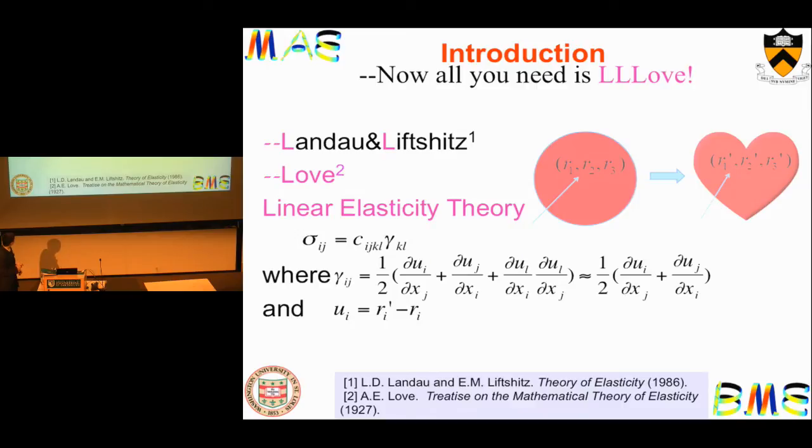And in linear elasticity theory, people just throw out the higher order terms, and the constitutive law simply states that the stresses are linearly proportional to strains, and that's like a 3D analogy of the well-known Hooke's law. So force is linearly proportional to displacement in 1D.